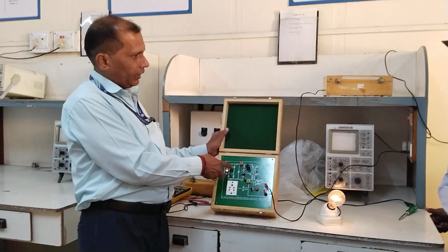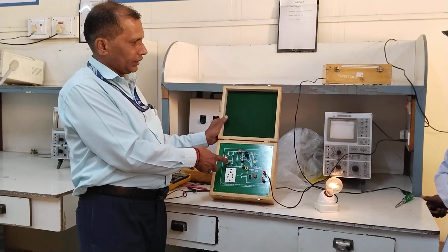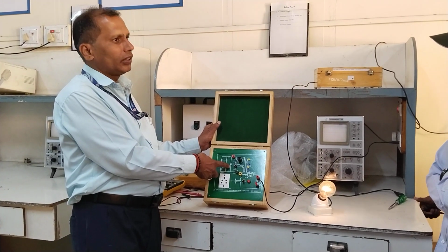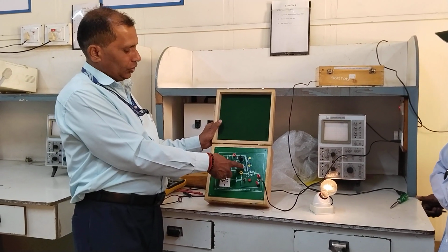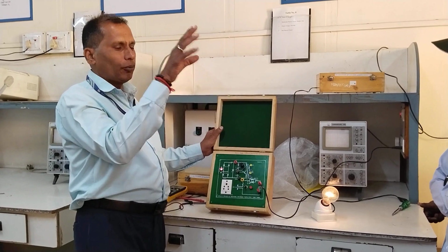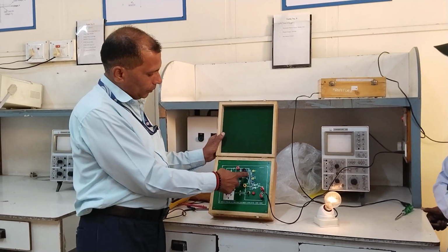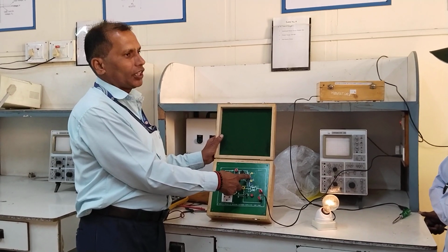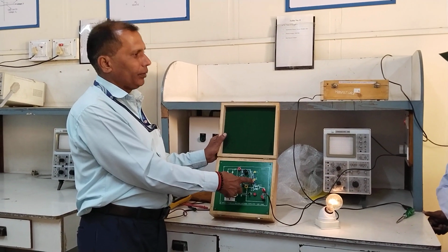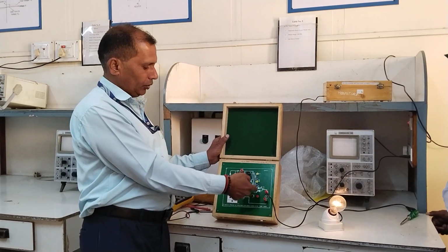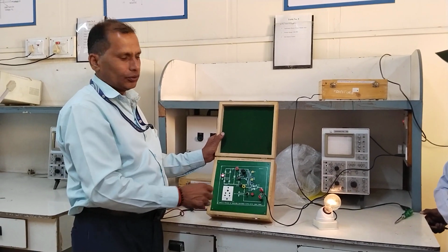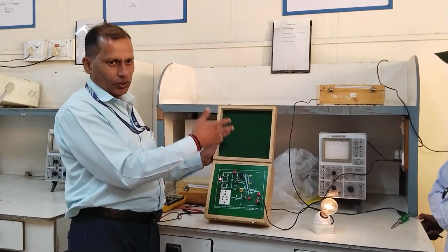This is an uncontrolled rectifier, a simple PN junction diode. Then a zener is there to make the output voltage constant. Then the UJT is there, so you have a valley point and a peak point, and during that period you get a single pulse. That pulse is generated here, and this is the pulse transformer. One will be a positive pulse, the second a negative pulse, and these two pulses are given to the two SCRs. You can see these two pulses on the CRO also.